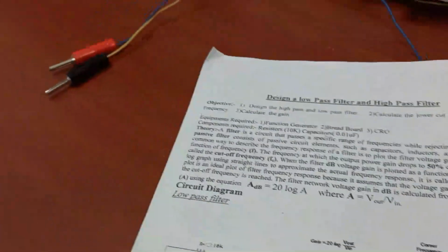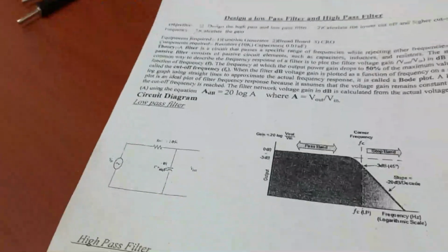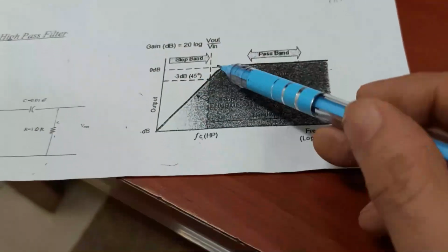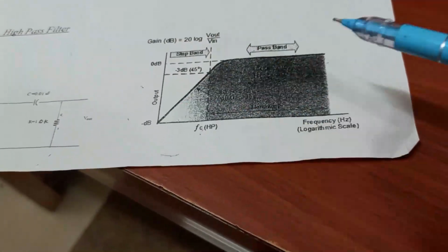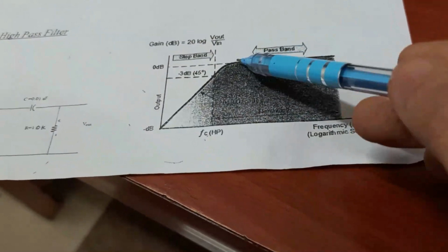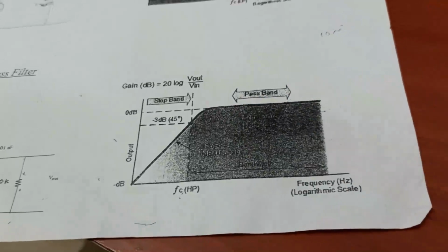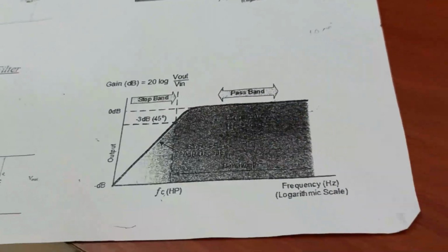Okay, so you can very easily see that what is happening is, in a high pass filter, whenever these low frequencies were there, my amplitude was getting attenuated, and at high frequencies my amplitude was remaining constant. Okay, this is how a high pass filter works.